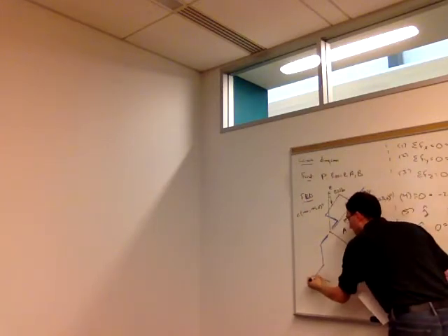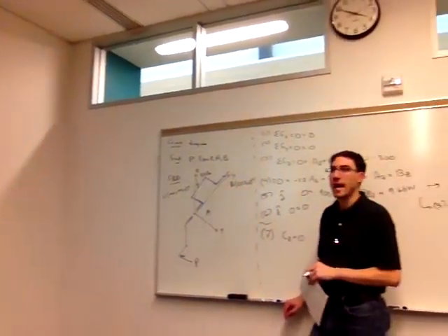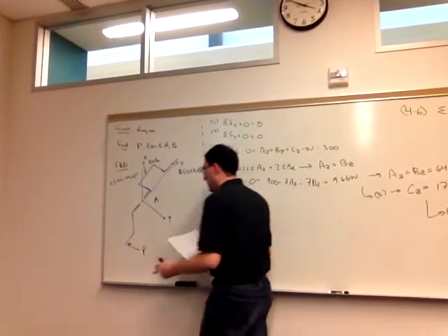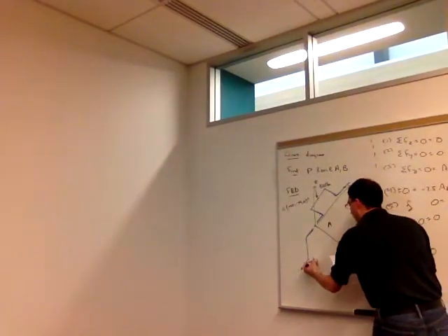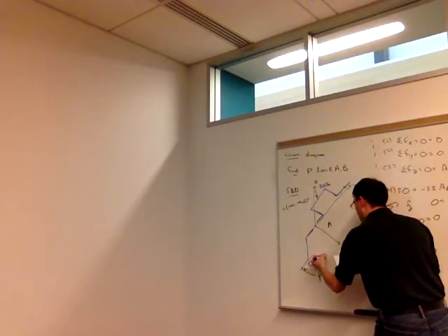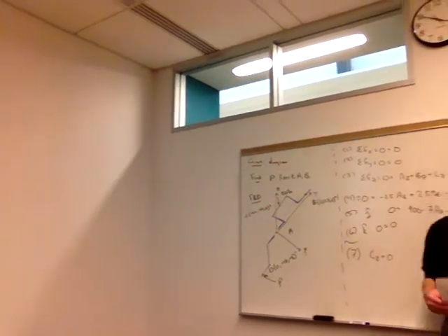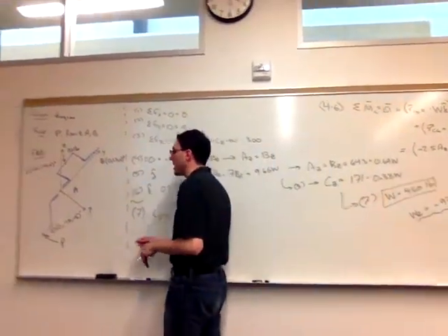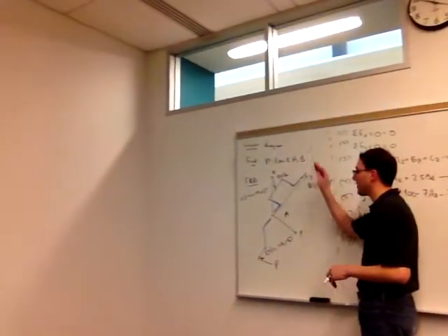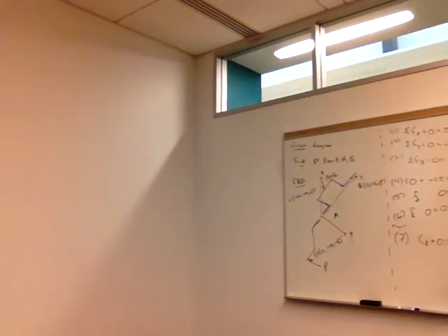A is at the origin, and then we're applying a force P that's parallel to the x-axis, and we're going to be applying that at a point D that is 0, -10, -8 inches. So I include the two applied forces, the 80 and this force P that ultimately we need to find. So we need to know what's happening at A and what's happening at B.